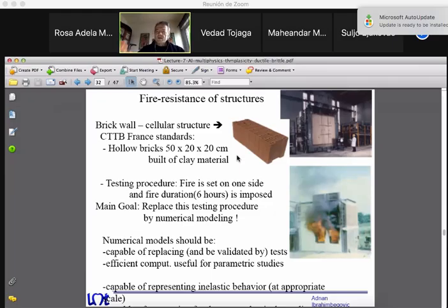It's not simply a 3D solid material, but rather it's like lots of these parois, what you call separation type of layers that are built together in the horizontal way and the transverse way. Typically, those that go into the longitudinal way are stronger than those going into the transverse way. So there's lots of anisotropy, at least orthotropy. There's one behavior in the direction of the wall, and there's one behavior perpendicular to the wall.